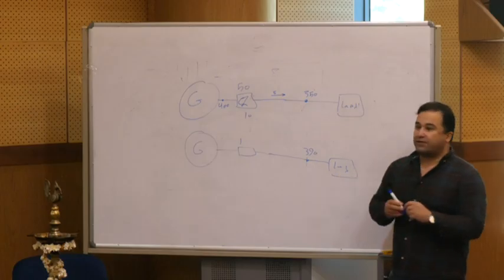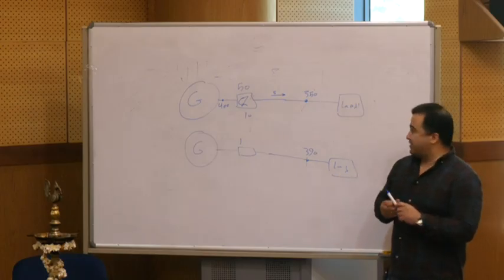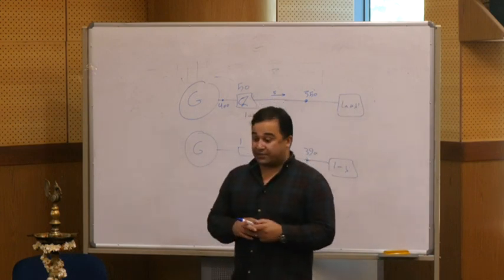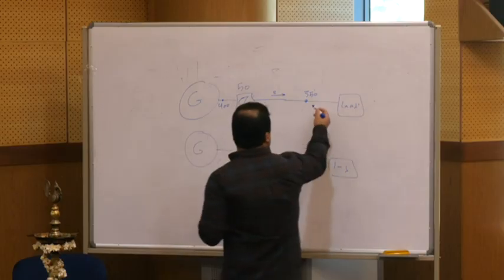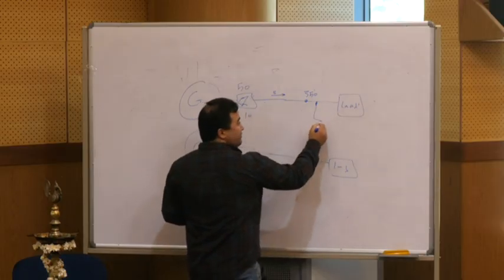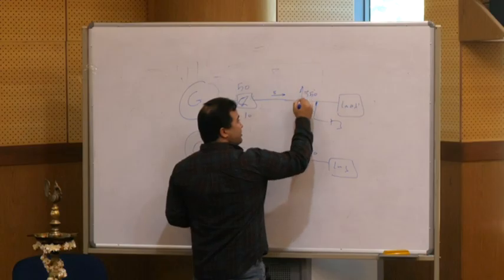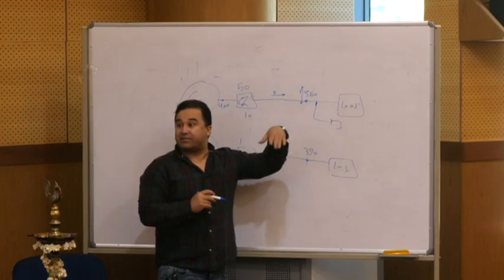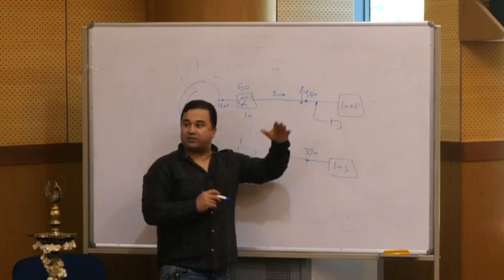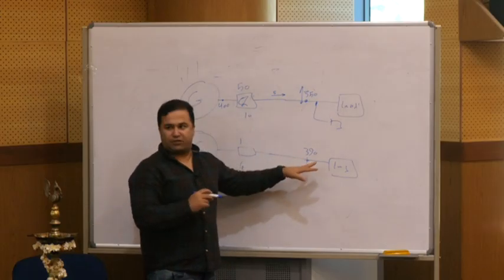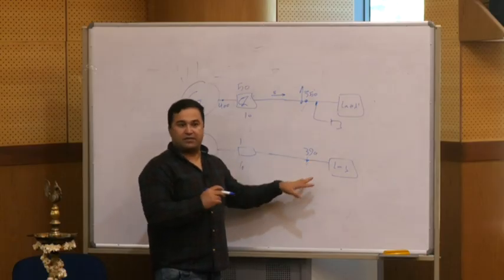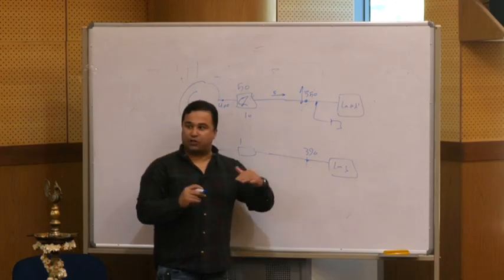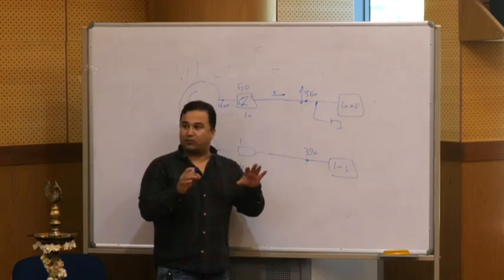Because the standard level is 400, and the voltage drop here is 10 volts, so we don't have too many losses. In the other system, if I have another load, it changes the voltage too much. So the voltage is unstable because it fluctuates based on the change of the load. But here it is not that much. So the grid is stronger. The voltage is not that much affected, so we have quite a stable voltage.